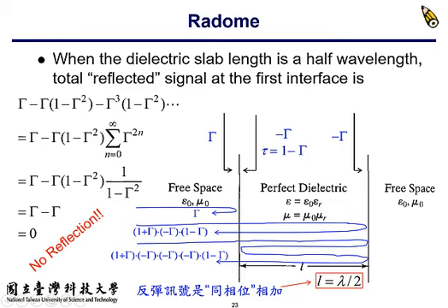So here we have an incidence, and at this interface you will have a reflection because of the difference in the intrinsic impedance. So here is the first reflection term. But at the same time, the rest of the energy goes into the second transmission line. So this represents the energy that goes into the transmission line. And some of the incident energy that reaches this end is still transmitted to the other end, okay?